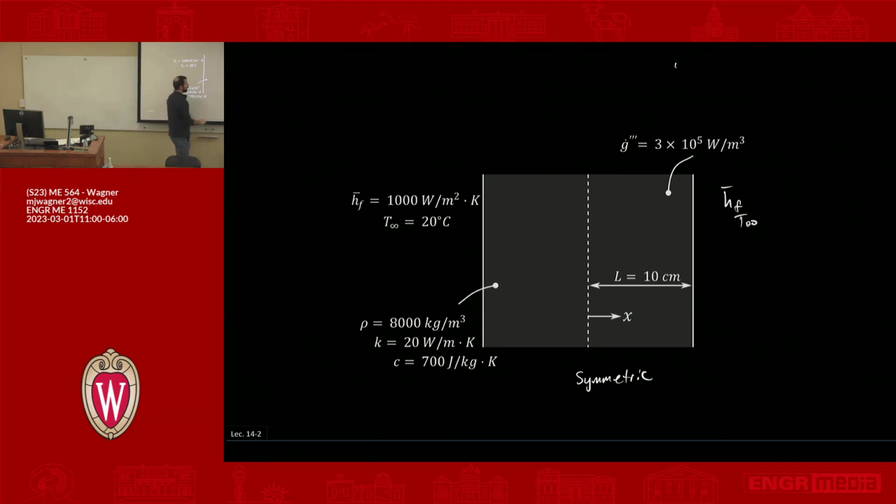And so what you would expect to see is a temperature profile that goes down here on the edges, goes up in the middle. It's symmetric, so dT/dx is 0. You get this kind of parabolic shape that's appearing in this problem. So that's what's happening before whatever disturbance occurs. And then at time equals 0, we have these two conditions that change.